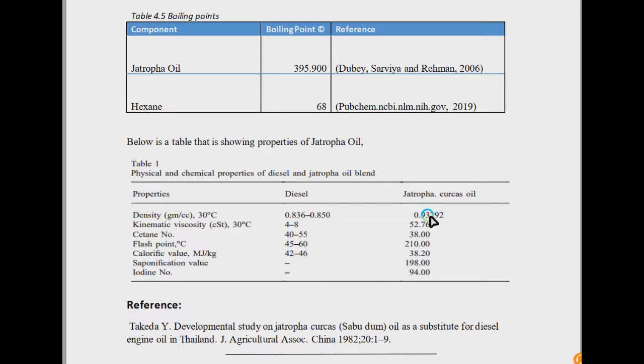Now, most commonly, a person facing the design of a seed extractor using the solvent technique will in most cases ignore the mass transfer rates, the equilibrium capacity, the mass transfer stages, or the contacting time in the extractor, and will directly move toward this type of design I am showing first. Then I will show what correction is needed in this design. So the desired capacity, as I have told before, is 21,742.18 kilogram oil per hour.